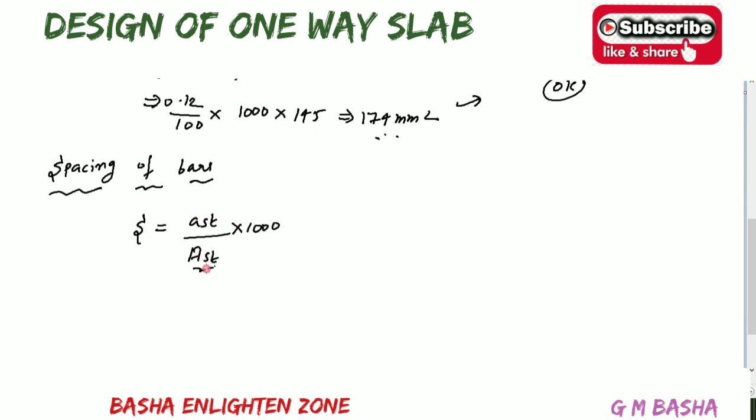So what about this capital AST? It refers to the value you get, that is 294 mm square. And what about small ast? That is pi dia square by 4, where you assume the diameter of the bar. We are talking about the main tension reinforcement. Here I am assuming a 10 mm bar. If the moment is somewhat higher, you can assume 12 also. So pi into 10 square by 4 divided by 294 into 1000, you will get the spacing of 267.1 mm.